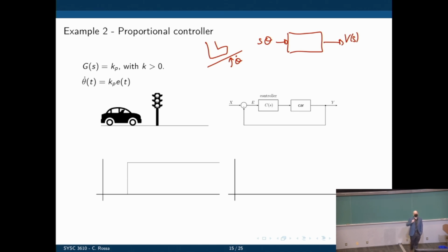So think about the Bode plot then. This is some sort of Bode plot response. Once the input is slow, the output follows it. Once the input is fast, the output is attenuated. Exactly. Once you increase the frequency, the car has less time to react, so the speed is not going to be affected much. It works exactly like in a Bode plot, where for a certain range of frequencies we see the output responding, and for a higher range of frequencies the output doesn't respond as much.